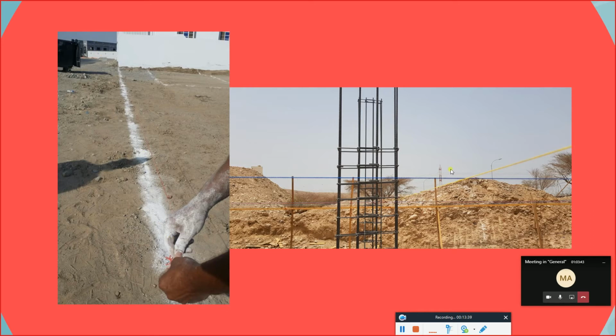Now if you can see here, we have a yellow thread, we have a blue thread, different threads are there. So wherever they are intersecting with each other, we can say that this is the position of a column, or this is the position of a foundation. This is going to make it very clear for us wherever there is an intersection, and in our plans, in that particular intersection there is a column or a foundation. I'll know that this is the place where I need to put the column or the foundation in reality.